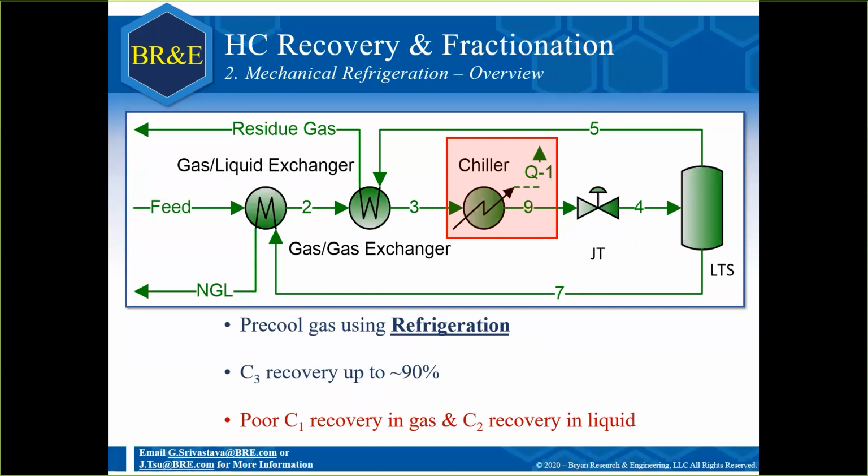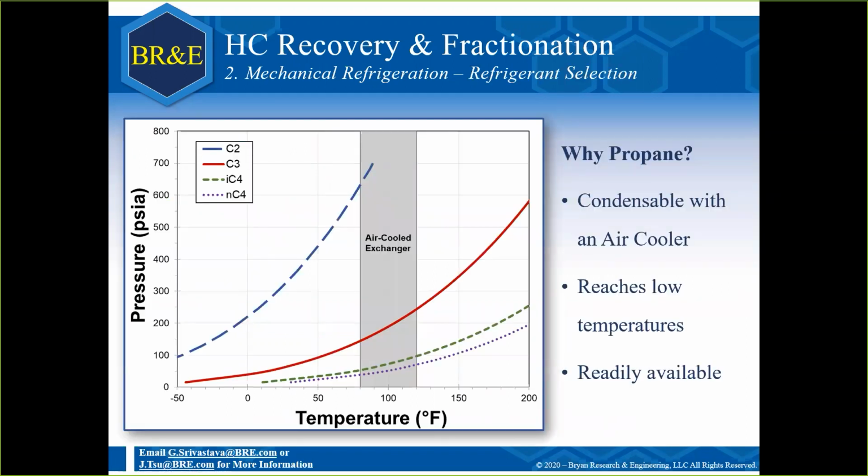So before we move on, I want to bring up the fact that, what is this refrigeration that we're doing? Well, typically, we are using some sort of mechanical refrigeration loop, and we generally use propane. But why do we use propane? Why not ethane? Why not butane? Why not methane? Well, it's to do with how economical it is. For example, propane, the red line over here,